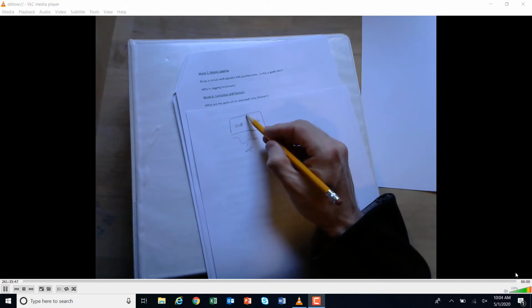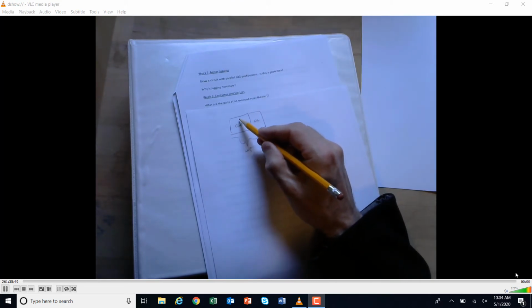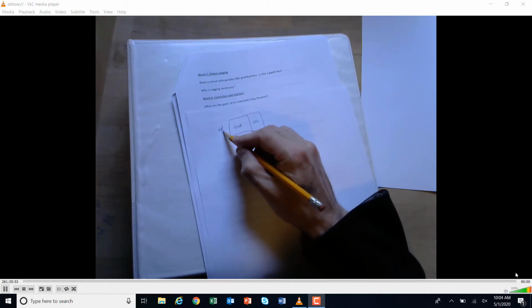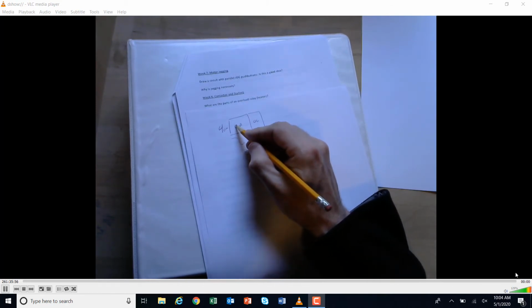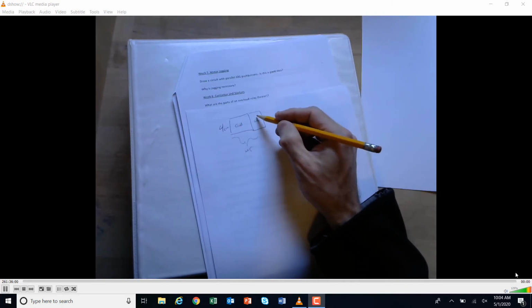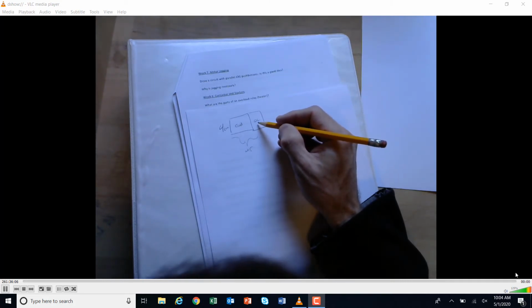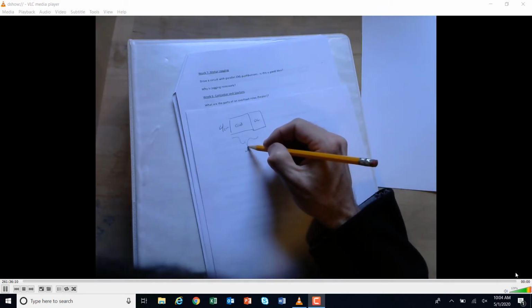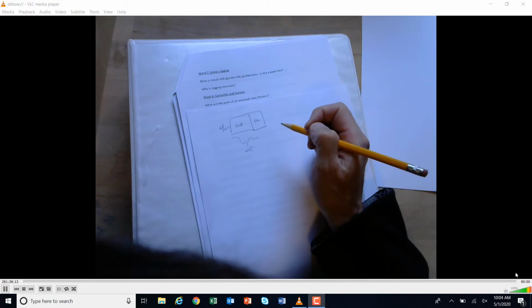And so the basic parts of this contactor right here are going to be the contacts. Remember, there were going to be 4 contacts on here: 3 main contacts and an auxiliary contact, right? And then this overload was going to have a heater and overload contacts, probably normally open and normally closed, okay? And then the motor starter was all this put together. Maybe there were even more additional auxiliary contacts and stuff like that.